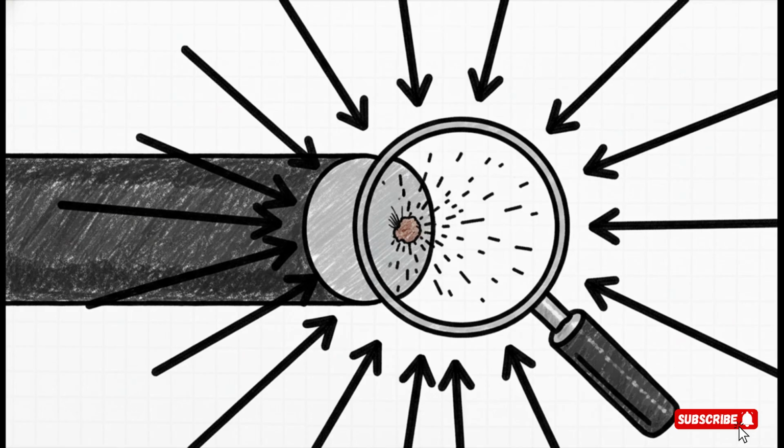Now, one of the most critical factors of all is the ratio of the cathode area to the anode area. And the point on this slide is absolutely vital. A small anode connected to a large cathode is the absolute worst-case scenario you can have.